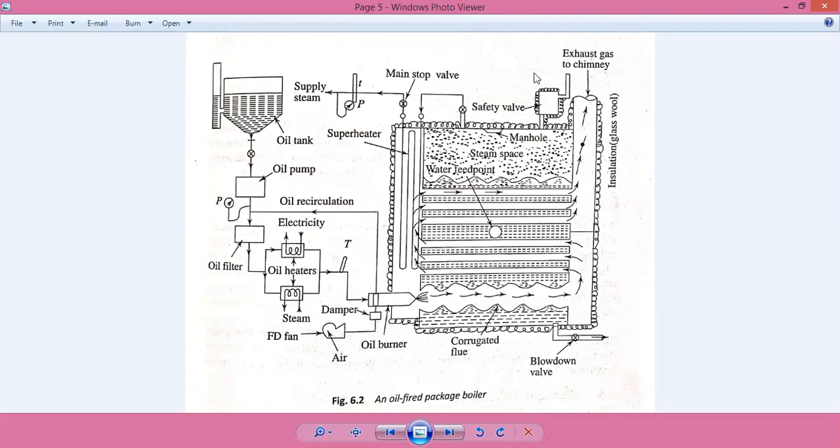The steam thus generated surrounds the tubes through which the hot flue gas is flowing, which transfers the heat to the water, converting it into steam, and with reduced temperature the gas is exhausted to the chimney. The whole set of tubes as well as the whole water drum is inside a single housing, along with a coordinated flue through which the initial flue exhaust moves, because it transfers the heat to the surrounding water in a better form.